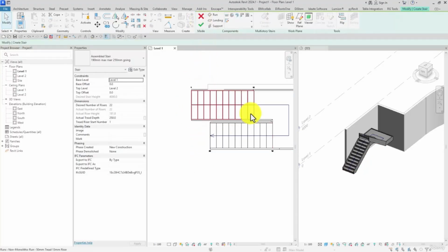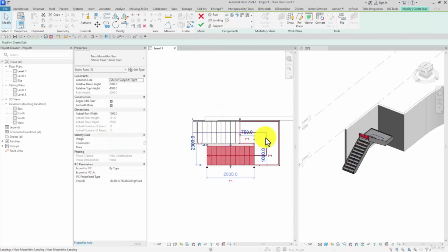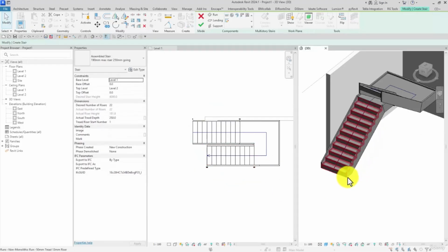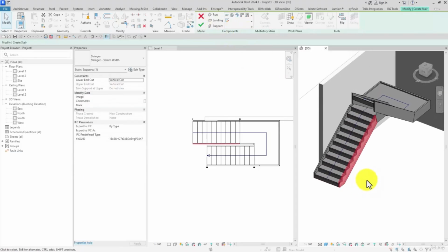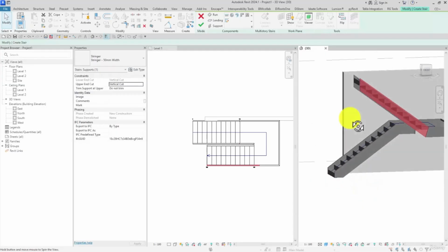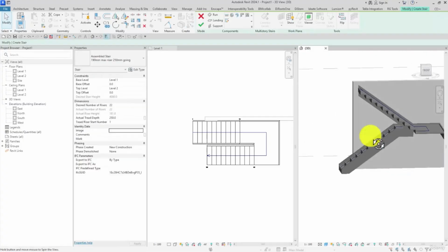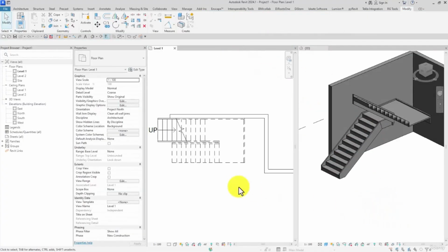Again I open the sketch mode, and note that here we got all of these stairs separately. We can edit them separately. And also we can select the stringers separately before finishing. Check it out. We can select it independently of the others and edit them, modify them, whatever. Or we can even delete them. Check this out. Deleting the supports and clicking on finish to save the changes.